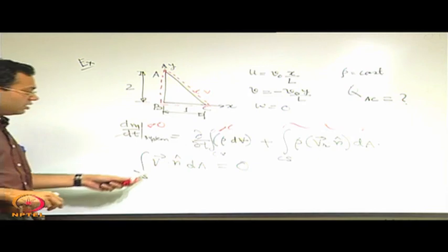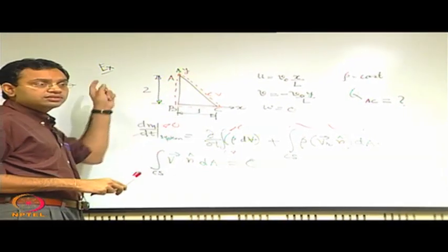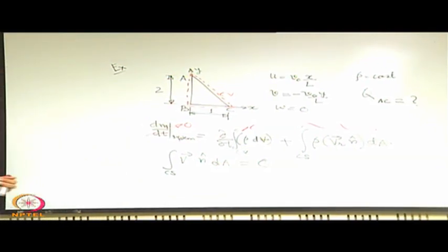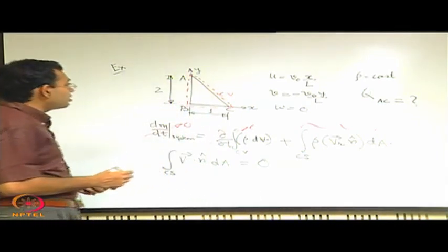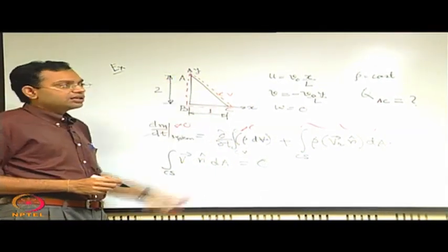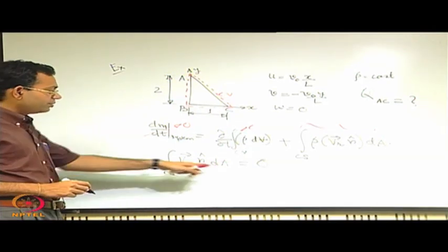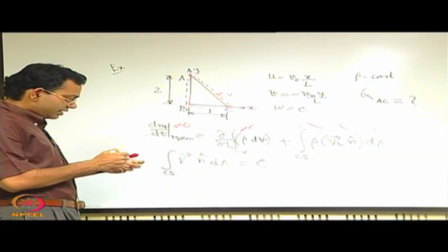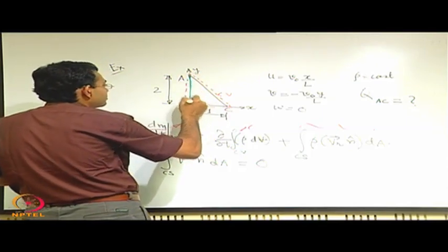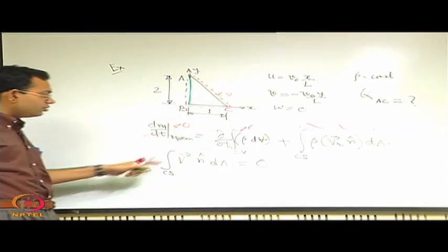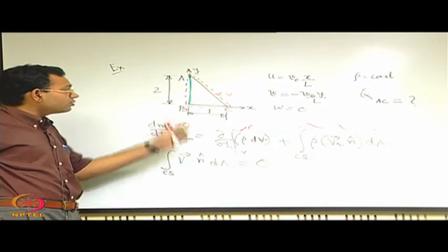So, this now we may break it up into 3 parts, because the control volume has 3 different distinct oriented surfaces. So, you can write this as the sum of the effects of AB, BC and AC. So, for AB when you write, what should be this corresponding expression? So, let us identify where that AB is. So, you are looking for this face, you are interested to find out what is V dot n, integral of that over the entire area.